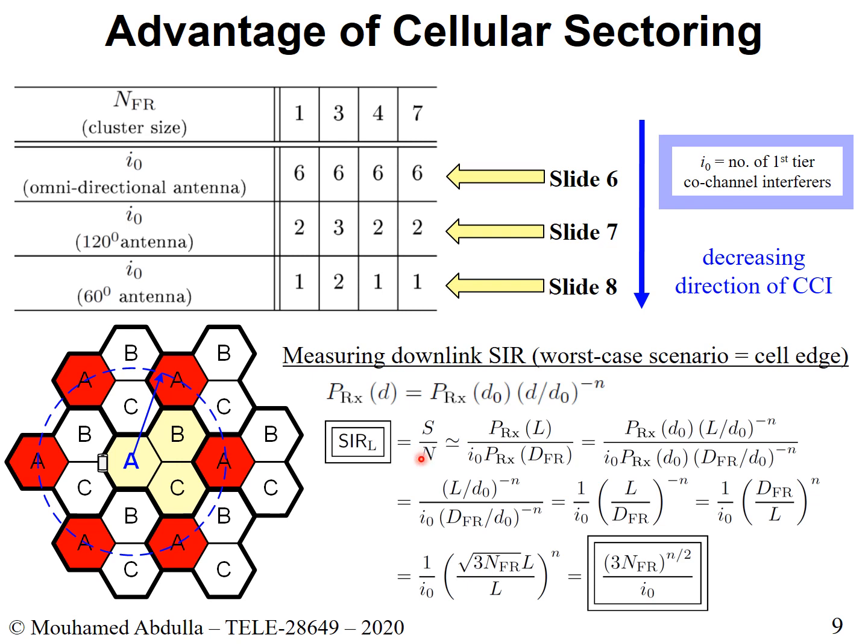S basically means the good signal that you are getting from your transmitter. So essentially here, you could simply replace it by the power received at a distance L from your transmitter. The transmitter is this one here, and this is the receiver. So the power received at a distance L. And for this, you could simply use this. So whatever you have here, except instead of D, enter L and then plug it in here. So this is just some constant, just rewrite it. And then here you enter L over D naught to the power of minus n.